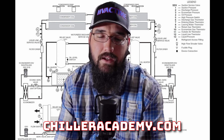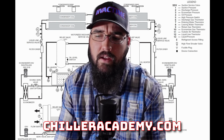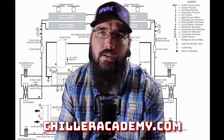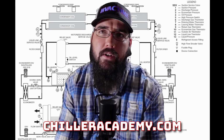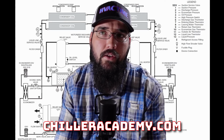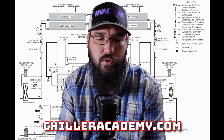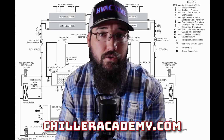They need to maintain a minimum differential across them, in order to keep the bolts properly torqued isn't the right term, but to keep enough pressure against them from suction to discharge in order to help them compress properly. And they'll get a bit loud and rattly if you start running really low differential pressure from suction to discharge.